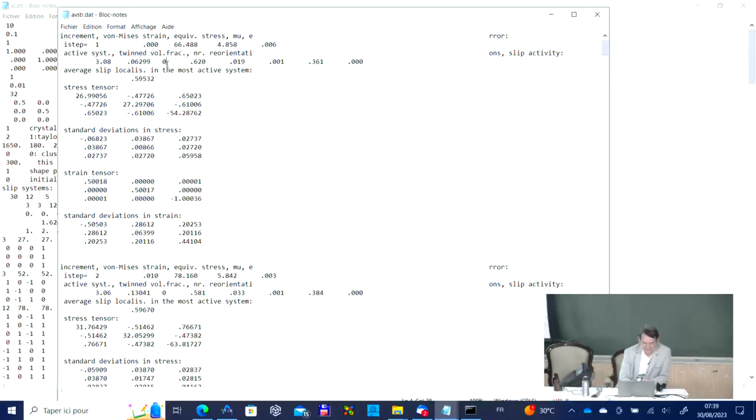Yeah, I will. And that so-called all-twinning variant approach is extremely successful. So much that the texture predictions are of extreme quality. Even individual initial grains, their activity, how they are twinning, which variants appear, with what volume, could even be predicted with the VPSC. That we did not expect.